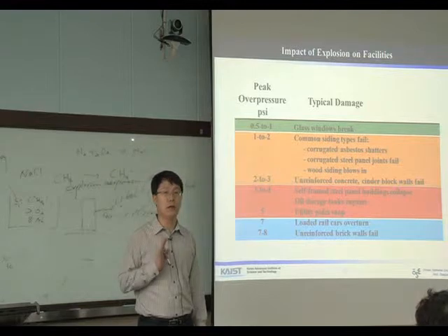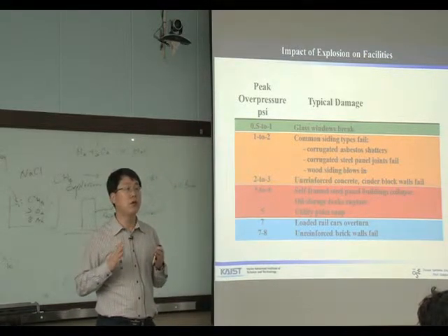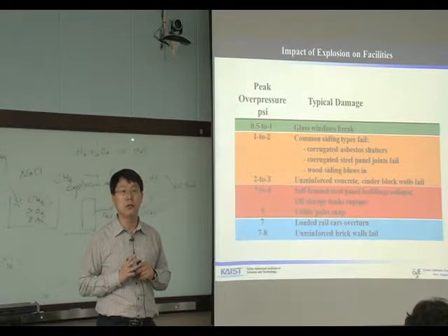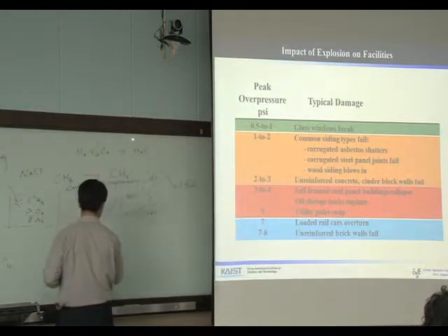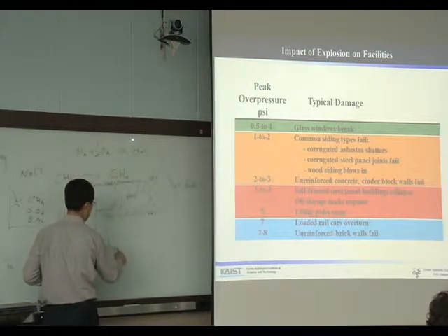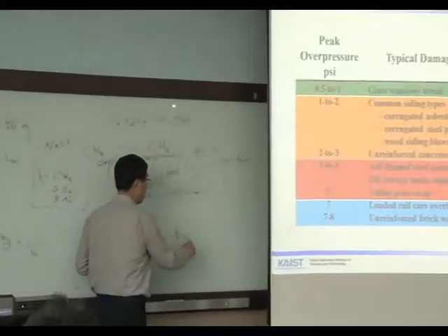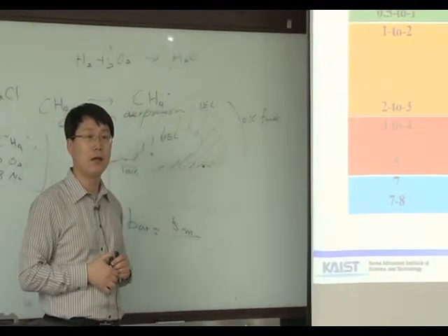So you should not confuse the magnitude of explosion pressure with the static pressure. 0.5 bar is just 5 meter hydrostatic head. Okay?